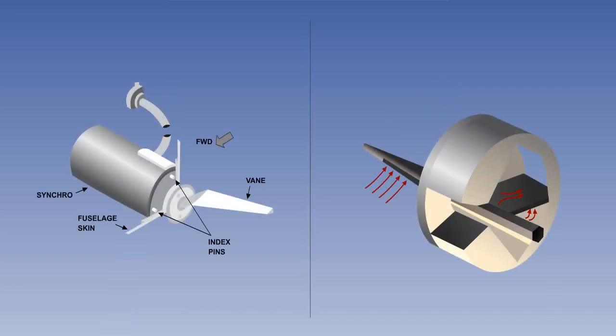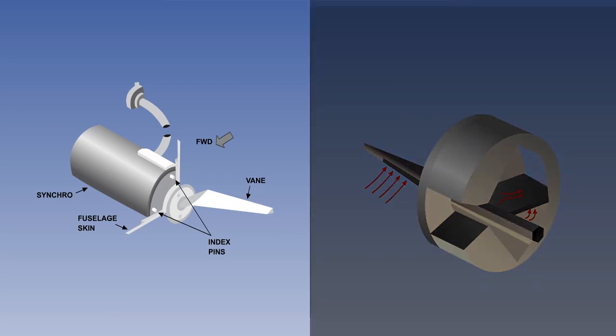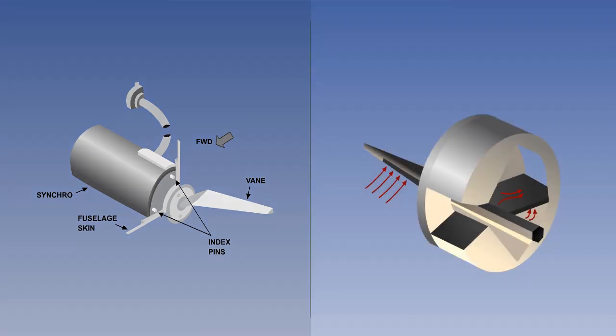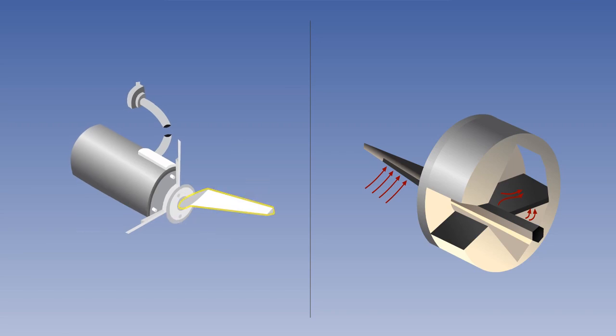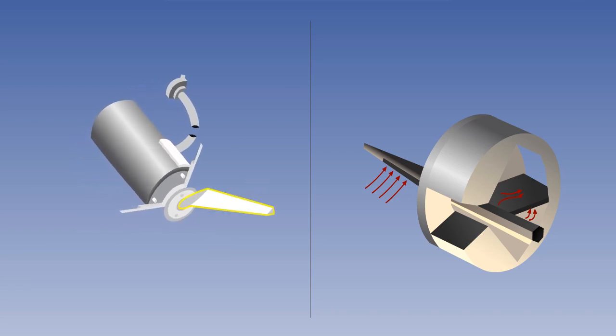As previously mentioned during the components phase, we are now going to learn about the angle of attack sensing probes. They are positioned on each side of the forward fuselage with two basic types in use: a vane type or a conical slotted probe. Both are protected against ice formation by a heater. The vane detector is a counterbalanced aerodynamic vane, which positions the rotor of a synchro, which is used to measure the subsequent angle. The conical probe protrudes from the side of the aircraft into the airflow.